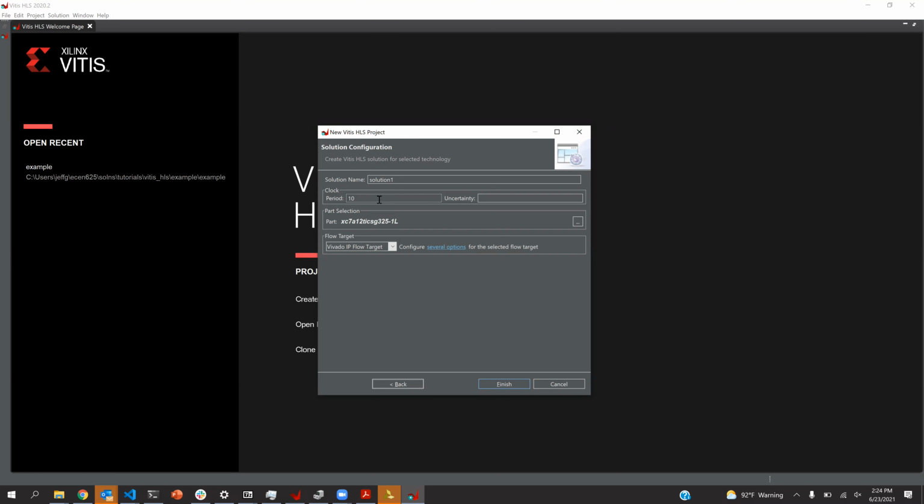What's neat is that this tool is going to make the Verilog for us. We tell it what part we're using and what frequency we want to meet, and it builds the state machine such that it predicts how much work it can get done in each clock cycle, but still meets the frequency target.